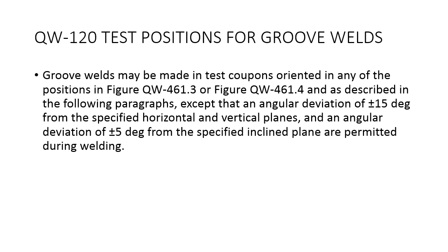Well, you're allowed a couple of degrees of angular deviation, up to 15 degrees. If you're welding vertical, you can move that 15 degrees either way before it becomes a different position. So that's what this is telling us. But test positions, very important. Like I said, they put it up front in the welding code here.